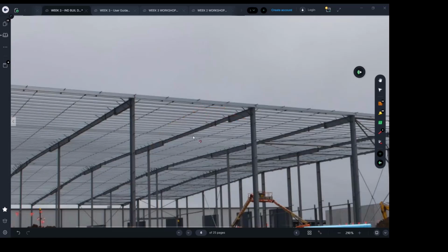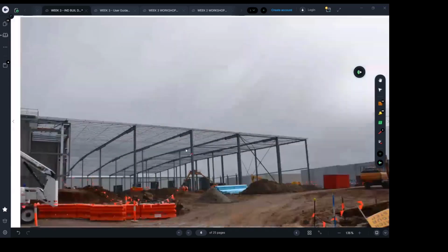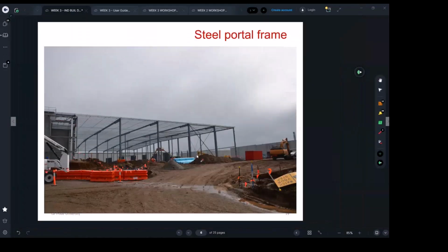When it's pushed upwards, the bottom flange will be under compression, right? And as we said, steel flanges or sections in steel are sensitive to compression. They can buckle. To stop that buckling, we're going to fly brace it. Fly bracing is actually supported by what? The purlins. So that's their second main important job in the frame.